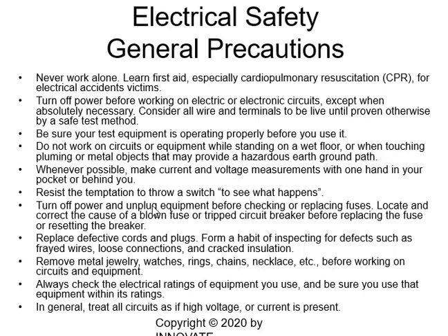Resist the temptation to throw a switch to see what happens. Turn off power and unplug equipment before checking or replacing fuses. Locate and correct the cause of a blown fuse or a tripped circuit breaker before replacing the fuse or resetting the breaker. Ask why this happened, and try to solve the problem. Replace defective cords and plugs. Form a habit of inspecting for defects such as frayed wires, loose connections, and cracked insulation.